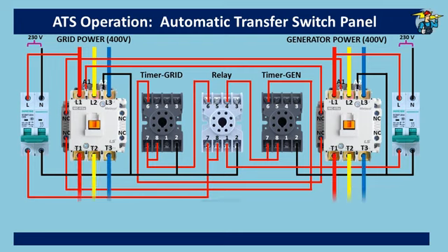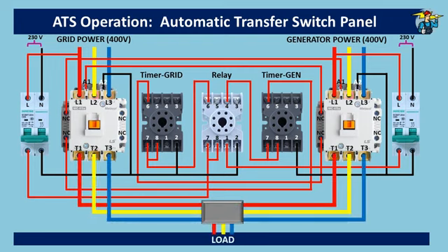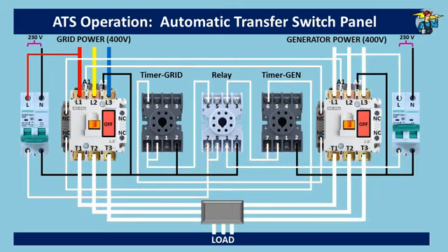Power supply to the load is shown here now, and the control circuit power needs to be kept on by switching on the two breakers. Let's see this condition now. Power supply is not on the load, but grid power is there, up to the contactor top. The issue here is, grid side control power is at off position. The neutral line is kept connected here, for easy understanding.